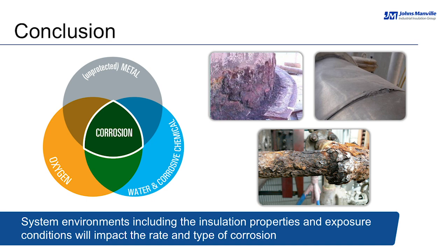So there's really no one-size-fits-all solution to corrosion. Material selection, whether it's metallurgy or insulation, is critical to designing systems with a robust defense against corrosion under insulation. And corrosion inhibitors can play an integral role in slowing corrosion and protecting the pipe surface. That's why looking at the system in the process is more relevant, and being able to vary the environment in which the system is tested is critical. As insulation manufacturers, we can design our products to be more water repellent, coating manufacturers can design coatings to be more robust, and end users can design their processes to most adequately comply with their environmental or process conditions.